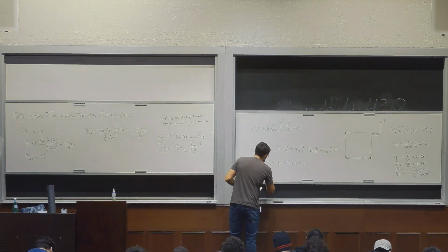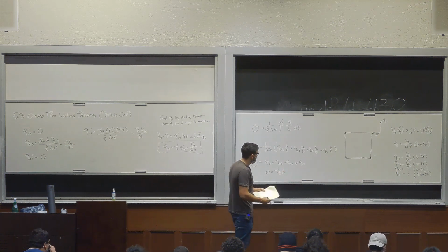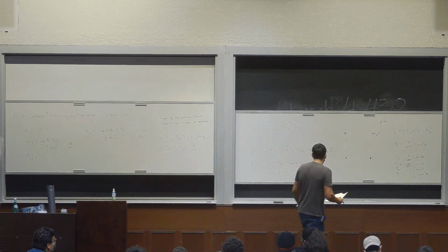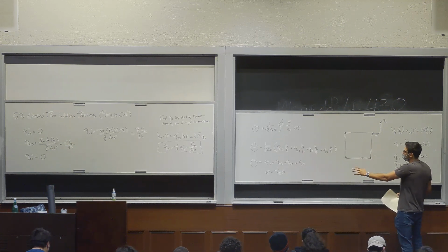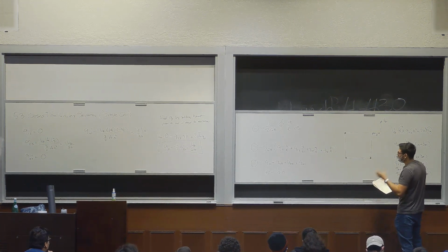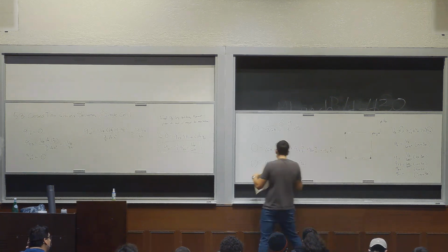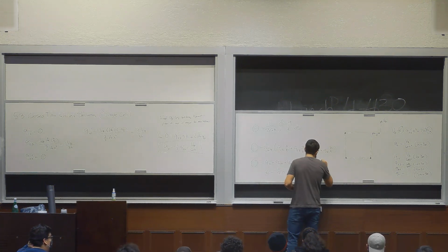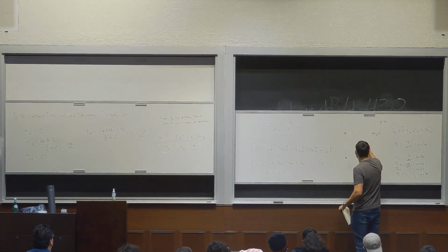We end up getting E equals -1/2 H. So if VZ was applied at the location E equals -1/2 H, then this wouldn't have any rotational deformation. It's important to remember that this is the shear center, the variable YSC. Remember the centroid was here.